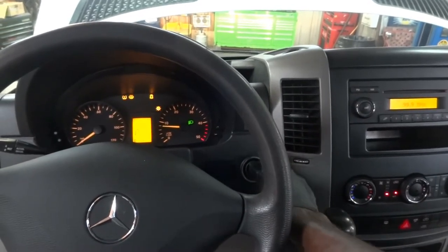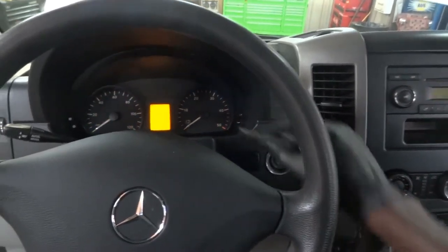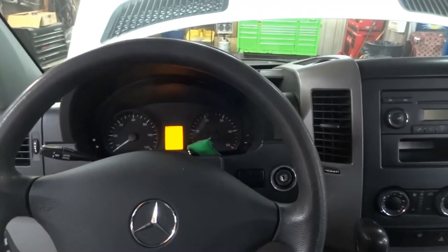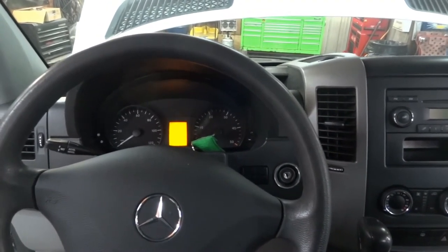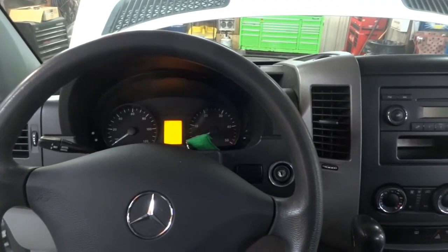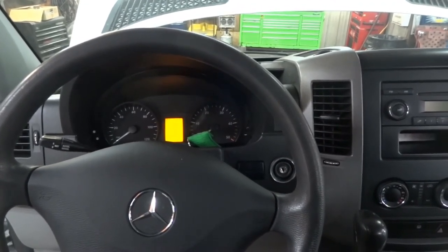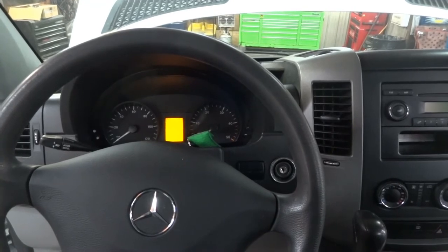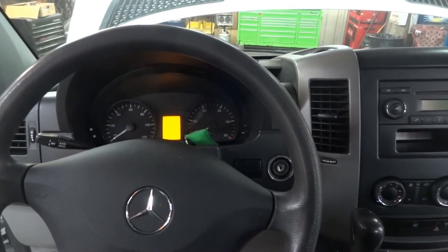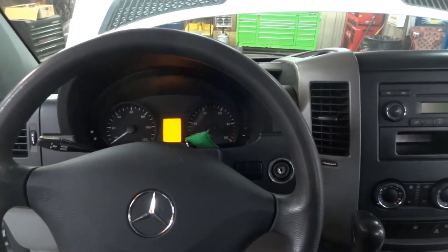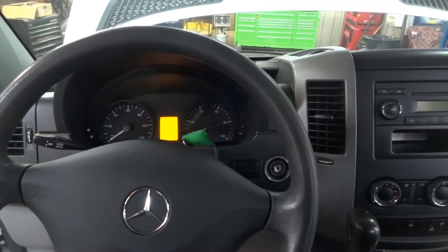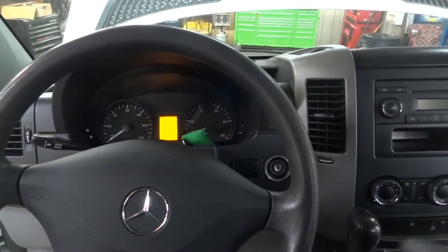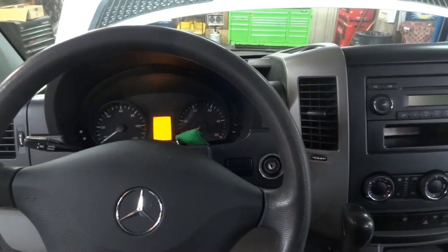Let's see how we're gonna attack this. Alright, so the van is off. How are we gonna fix this? Hopefully this is just gonna be a quick one. Well, there are a couple ways we can go with this. We can connect the scan tool to the van to see if we have any trouble codes in the air conditioning control module. Or we could also look at the wiring diagram to find out how this blower motor is wired. And we can also check a fuse and see how the regulator for this is wired.